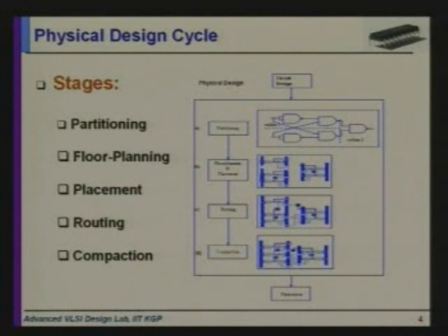In routing, there are actually 2 phases, global and local. In the global routing phase, we list out different channels and things called switch boxes, which we'll take up in the second part of this course, and find out the connections between two blocks, say, in a layout which contains two blocks at different places. So we find out the different channels and switch boxes through which these connections will be made. And in the local routing phase, we take each channel or switch box and make the connections.